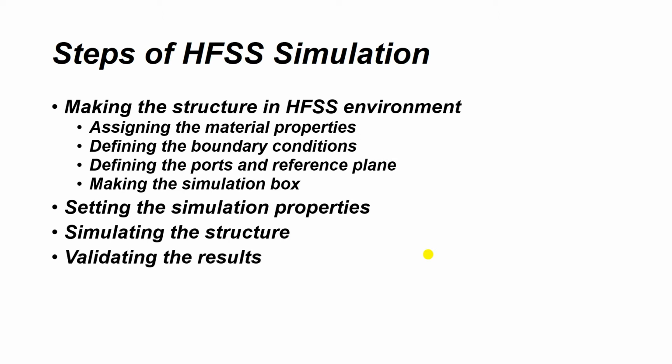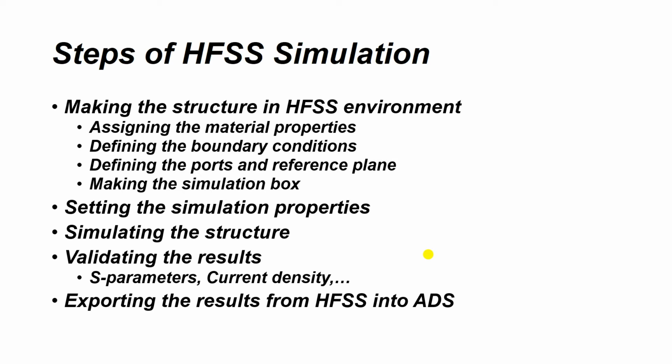The next step is to validate the results. So we have to check the results to see if they make sense by checking the S parameters or current density in different parts of the object. And in this video, we'll see how to export the results from HFSS into ADS in order to compare the results between these two softwares.